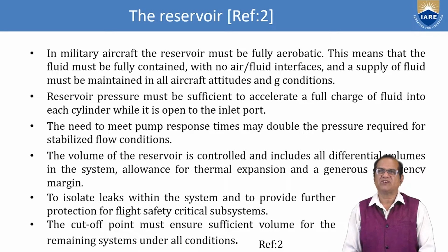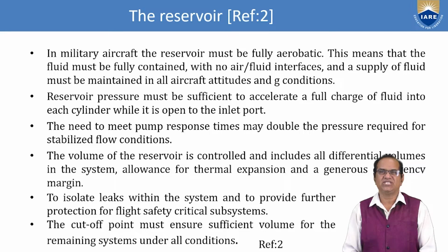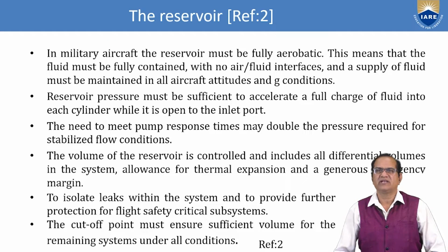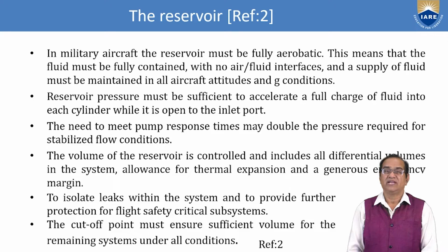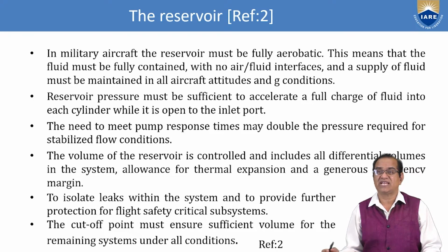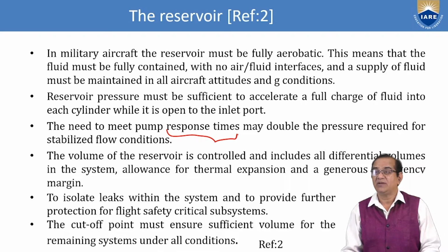Reservoir pressure must be sufficient to accelerate a full charge of fluid into each cylinder while it is open to the inlet port. The need to meet pump response times may double the pressure required for stabilized flow condition. The pump response time should be very fast.